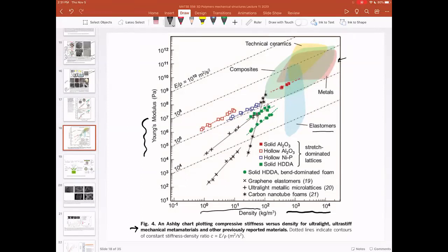So of course, if you need strength up here in hundreds of gigapascals, you're not going to be able to use a truss. But if you're really sensitive to density, if you want really light materials, say for space or for portable applications where things need to be as light as possible, you're not going to be able to get a solid metal or a solid plastic even that's light enough. You're going to have to rely on this material architecting to still maintain some sort of Young's modulus that you can design around while still getting really, really light materials.